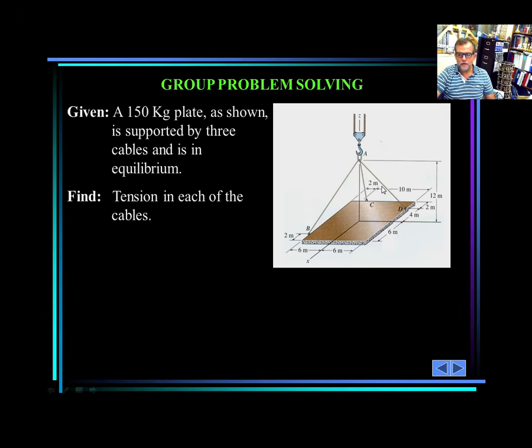Convert each one of the forces into Cartesian formulation, add them with the weight in x, y, z, and set the system of equations equal to 0, 0, 0. Solve for each one of them. How are we going to calculate each one of the forces in Cartesian notation? What do I have here? Distances everywhere, no alpha, beta, and gamma, only distances, nothing else. Distances, coordinates, position vector, unit vector: divide the position vector by its magnitude, multiply by the magnitude of the force, which are my unknowns, add them up and solve the system.